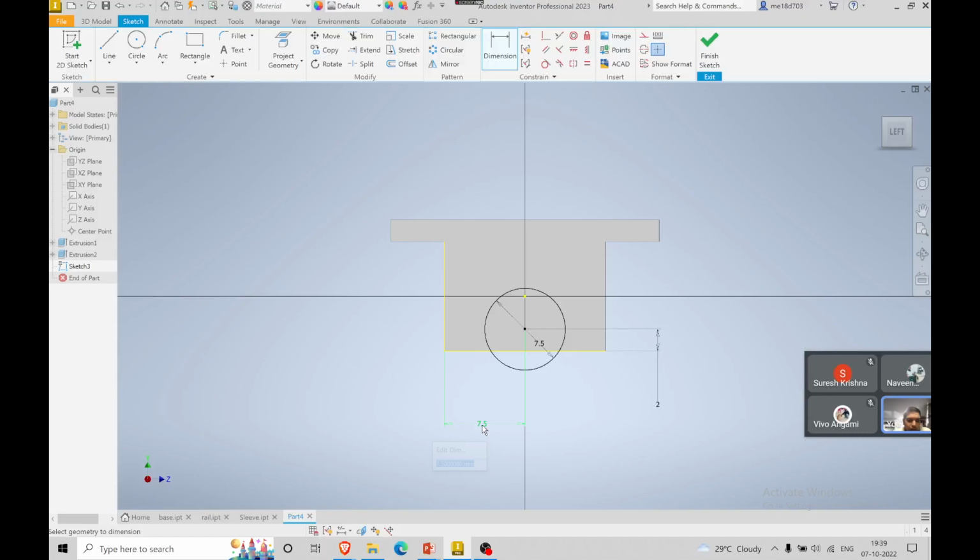So now I'm going to create 4 holes. So first hole I am creating, which is 15 mm, 20 mm means, so these two will be equal. So it will be 20 minus 15, 5 mm, 5 mm by 2 will be 2.5. And this same thing again, this will also be 2.5 because it's a square. 25 minus 25, 5 by 2, 2.5. So 2.5, 2.5. I'm going to create a hole here.